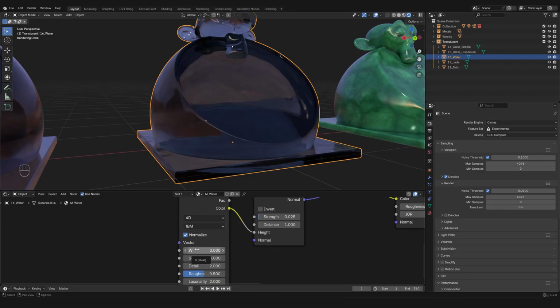Let me demonstrate, which is far easier to show than tell. So I'm going to click on this and then type the hashtag symbol. The hashtag symbol is what opens a driver. And then I'm going to type in frame. What this will do is create a driver, which ends up being of this color, this sort of purple violet thing. Tells me that there is a driver set up over here.